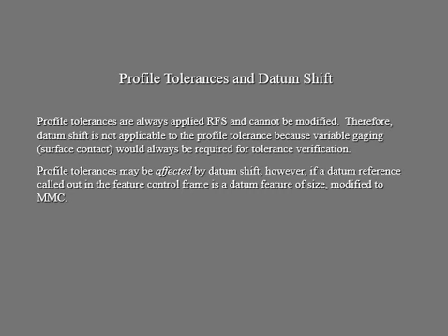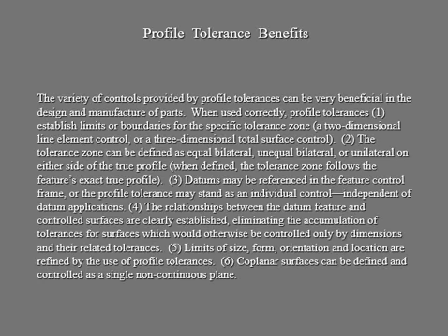So your profile tolerances are always applied RFS, and you can't modify. So your profile of a surface is the next thing that we will be getting into. Don't forget your symbol has a base. It isn't a line anymore. It is now a surface. So we'll go into profile with your related feature tolerance.